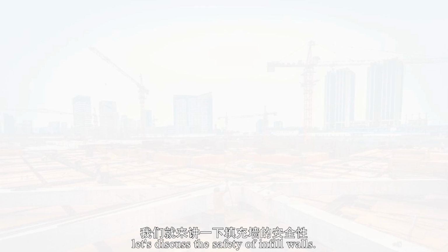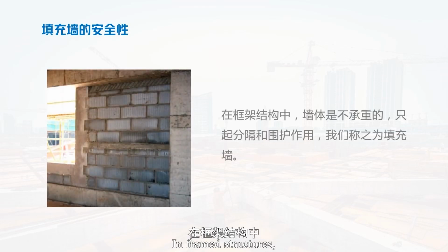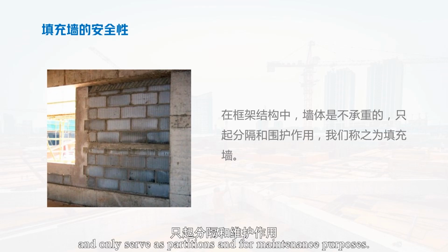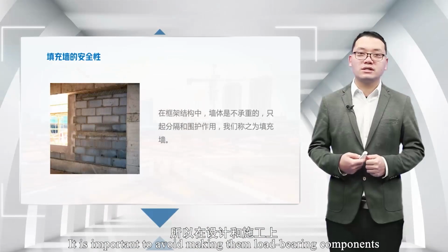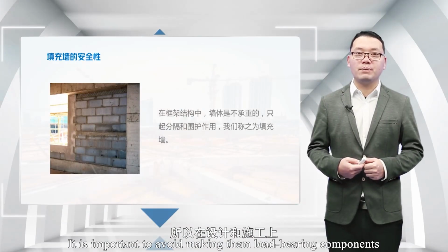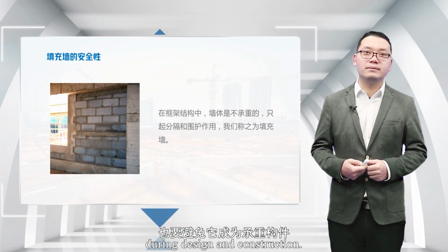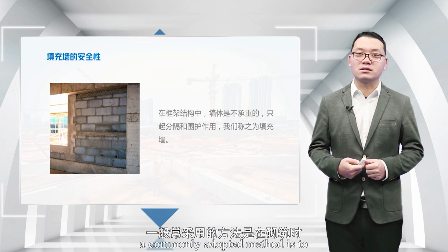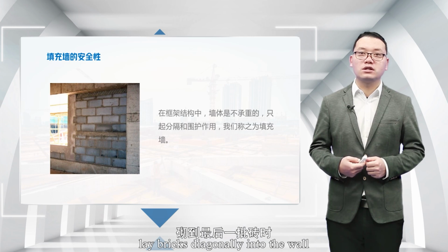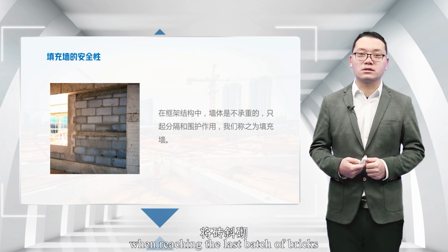Next, let's discuss the safety of infill walls. In framed structures, walls do not bear loads and only serve as partitions and for maintenance purposes. They are referred to as infill walls. It is important to avoid making them load-bearing components during design and construction. In engineering, a commonly adopted method is to lay bricks diagonally into the wall when reaching the last batch of bricks.